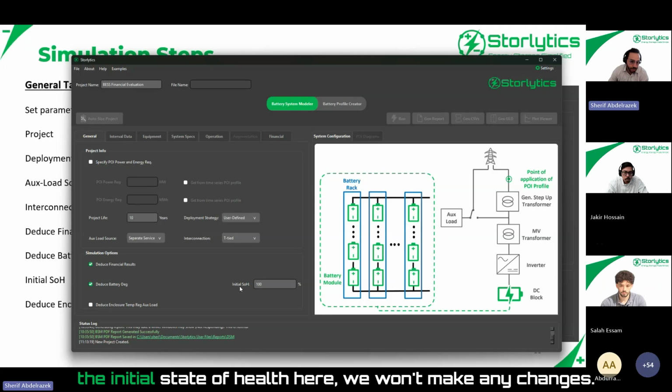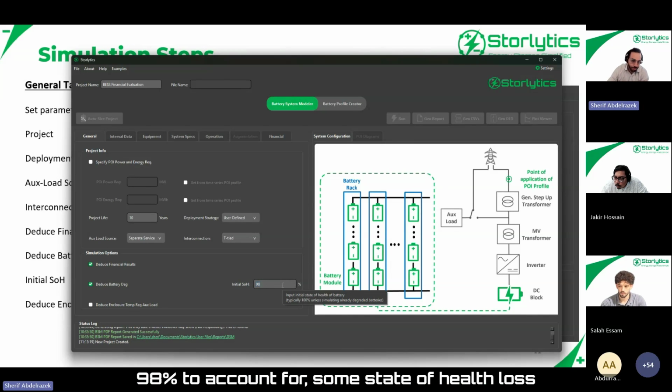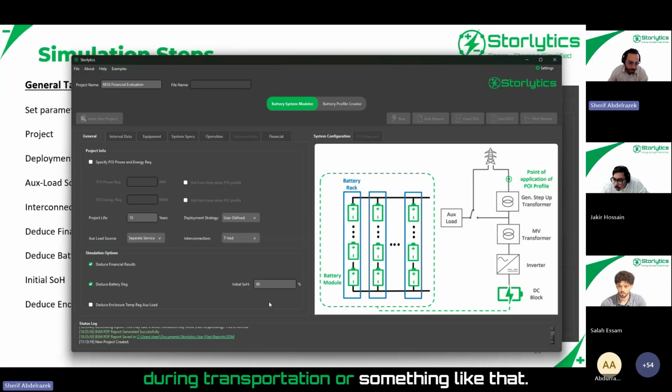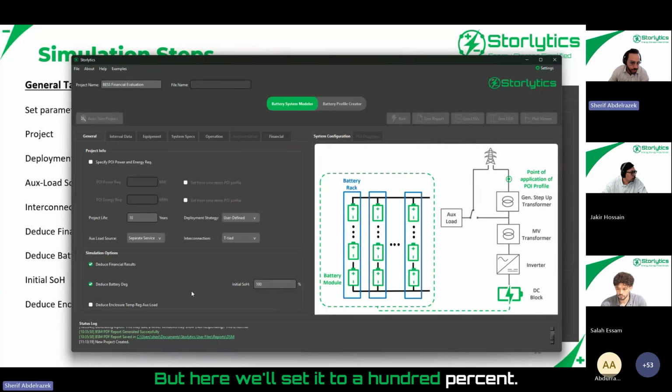For the initial state of health here, we won't make any changes. Its default is 100%, which assumes the battery cells are new. Some companies and users like to set this to 98% to account for some state of health loss during transportation or something like that, but really depends on your case here. But here we'll set it to 100%.